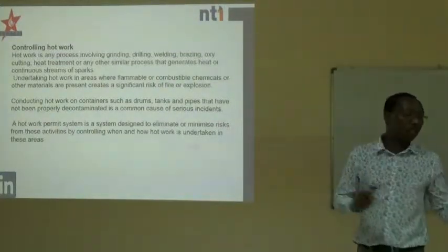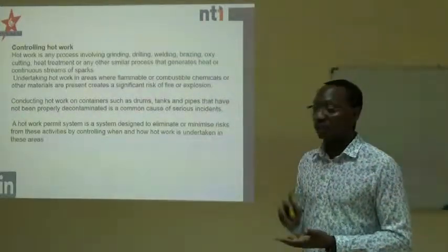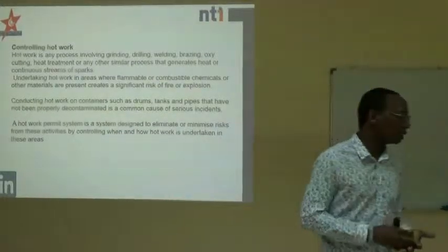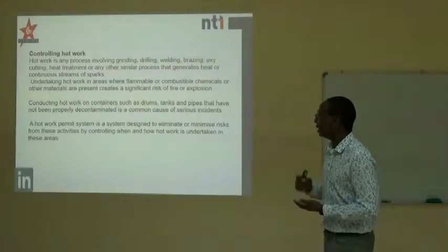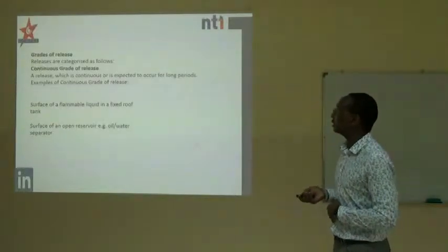So ladies and gentlemen, once again, I want to emphasize that when you know that you are doing hot work, mainly the guys in mechanical engineering or even electrical or instruments, make sure that where you are working, the system has been decontaminated. It is very important to make sure that has been done.